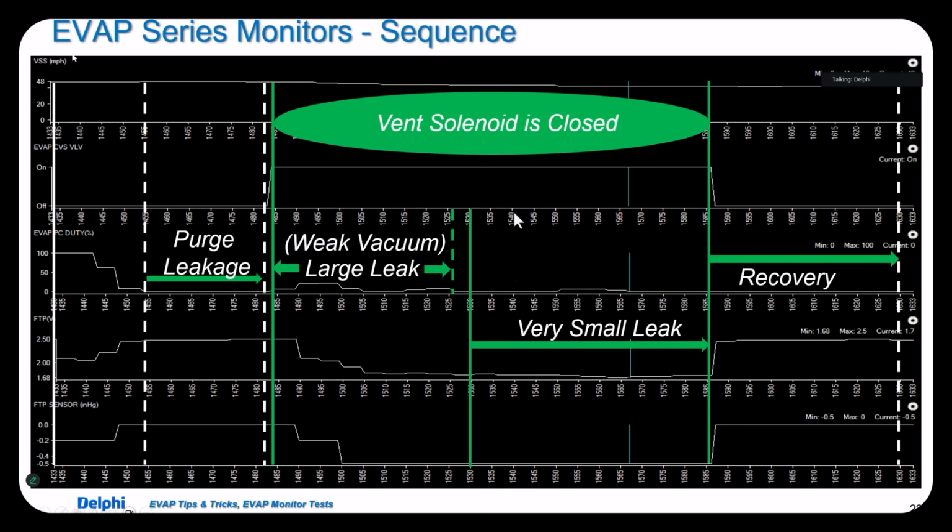Okay, here's a graph from Snap-on Scan Tool into their PC-based ShopStream, just to show you. This car, there was a purge check here. Basically, you shut it down. You look for any changes in the pressure sensor at this point. You notice the pressure sensor is steady. Because it's steady, the purge is closed. It knows it's not leaking.